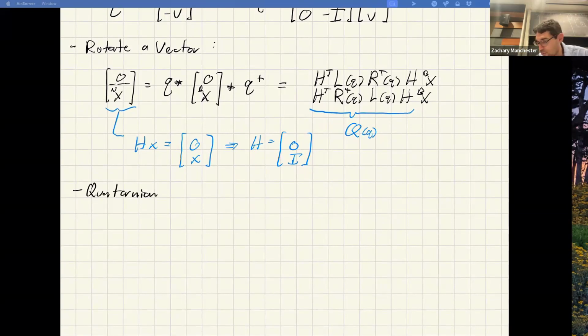So it shouldn't be surprising, and if I sort of force the issue, you could probably figure this out at this point, but it's super analogous to the rotation matrix case, right? So remember, rotation matrix, it's Q dot equals Q times omega hat. So knowing what I told you about the hat map and this little H thing here, you can probably figure it out. So for quaternions, it's Q dot equals, it's almost Q times H times omega, but there's a 1/2 in here, which we'll talk about in a sec.